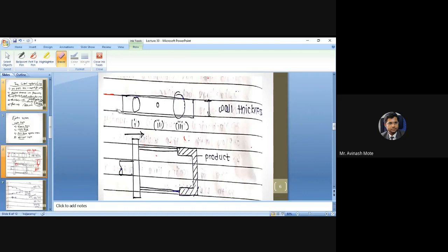And one more issue we discussed in compression molding is about the surface of the pin. It should not always be a plain surface. You can prefer a plain surface, but if your product is spherical shaped, the area of contact using this kind of pin will be less, so you need this kind of pin for the cylindrical surface. I will show it to you.